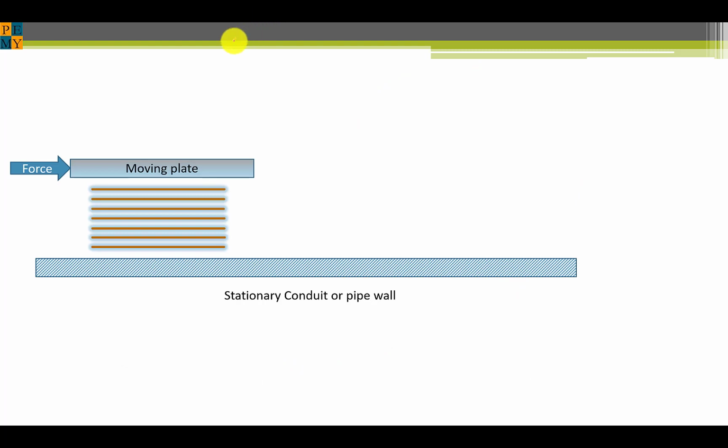Let's consider this setup that illustrates how viscosity works. We have a stationary plate down here with fluid in between it and a moving plate here. This plate is being pressed by a force and moves in this direction at a constant velocity u. Think of the layers as lamina. In fact, we're talking about laminar flow. As this plate moves, it causes these layers to slip past one another. The amount of drag between layers is, of course, related to the viscosity.